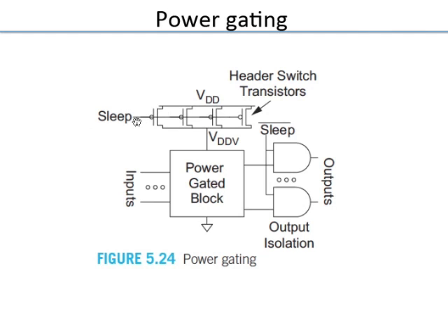Or maybe the sleep voltage, instead of VDD, could be slightly above VDD. For NMOS, when the gate voltage is less than 0, it will turn off the device even more. Similarly, for PMOS, if the gate voltage is above VDD, it will turn off the PMOS even more.